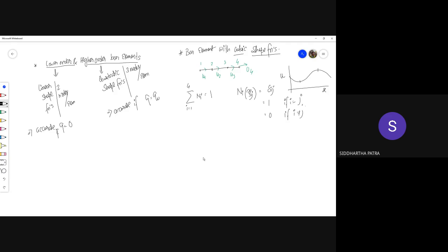So again, I can have my xi mapped from -1 to 1, and then the nodes could be at -1, minus 0.25, 0.25, and 1, right? So I can split that into three equal parts. No, this is not three equal parts. It should be -1 third and +1 third. Okay, and this is how the shape function should be.